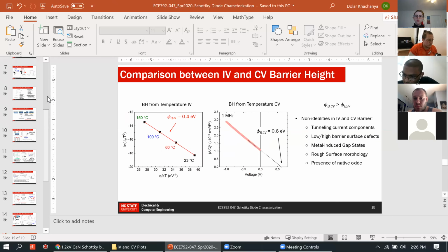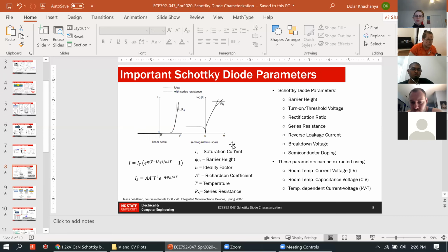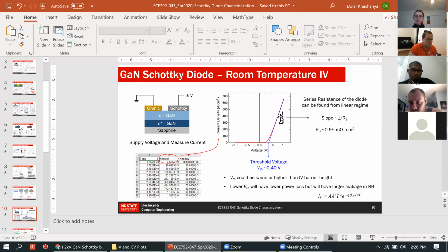And on top of that, you will actually see what is your threshold voltage, because then you can have an idea, okay, where your device is on and when you want to turn off the device, and what is the limit and what is the breakdown voltage. So you slightly apply lower than your breakdown voltage.